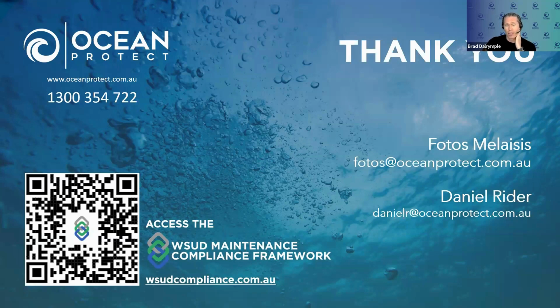Can you believe that? And there's a lot of stuff that we've learned, particularly around wetlands. Number one, you really should have GPTs upstream of wetlands to reduce sort of maintenance burdens and improve function. So I really feel as though there needs to be some sort of more live web-based guidance or framework on how to best design a whole range of assets, not just potentially proprietary assets.